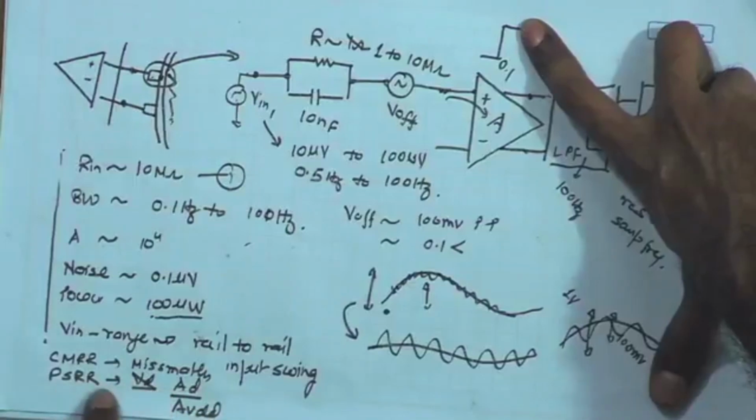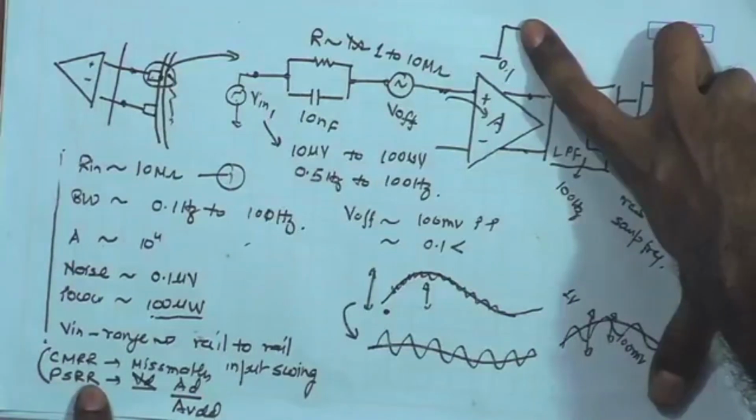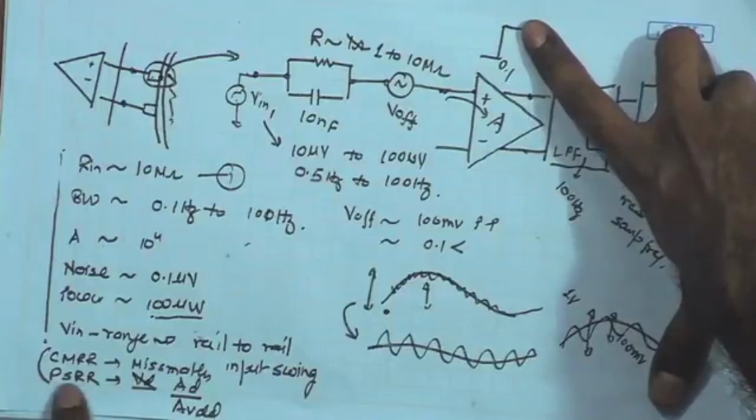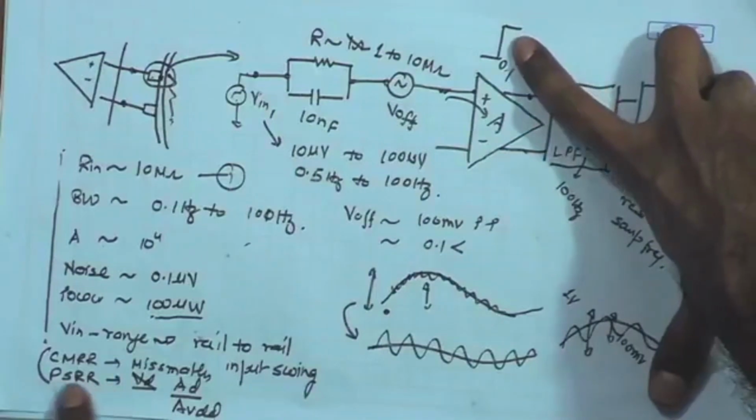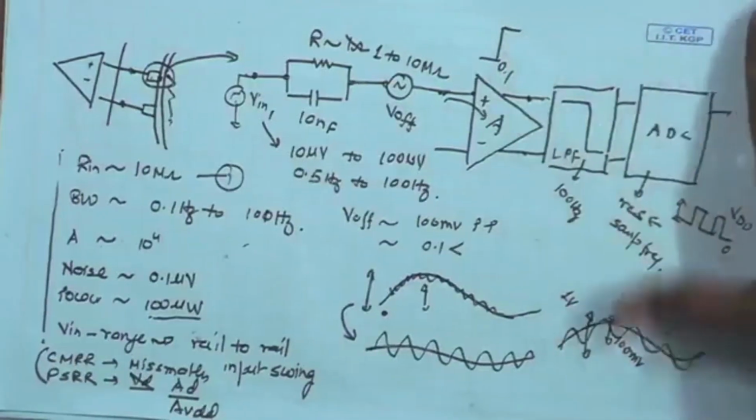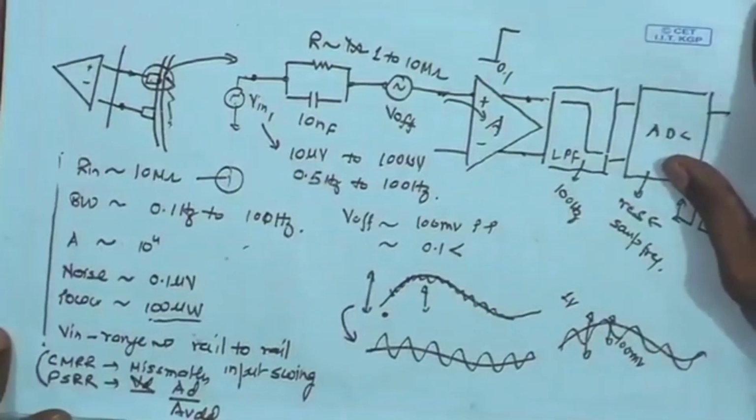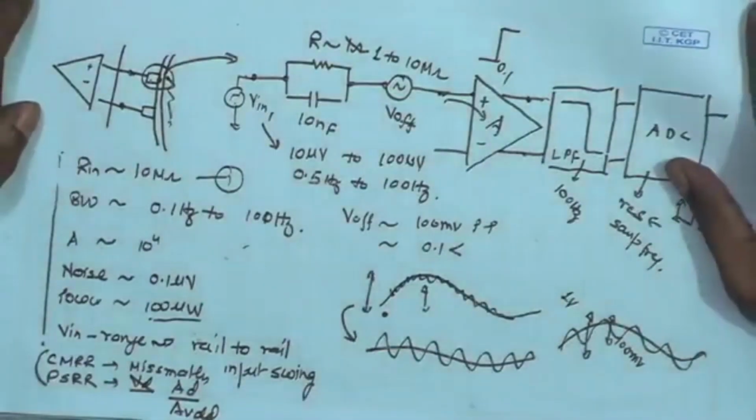We will see in subsequent discussion that these two parameters, CMRR and PSRR, are also influenced by the load conditions, and we will try to arrive at the expression for PSRR and see how the choice of load and the appropriate biasing topologies play a role in determining these two. So let us continue our discussion on the biasing scheme, the common mode rejection ratio and the common mode feedback in the subsequent session. We stop here before we start the next module.